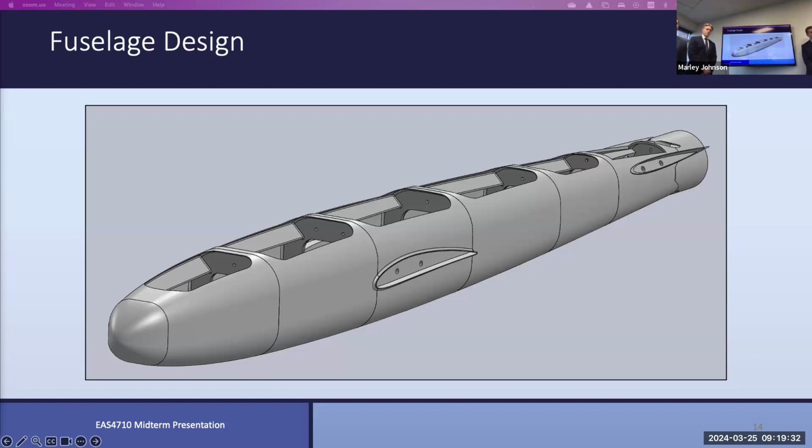So as long as you're able to show, back to structural analysis, assuming that all your load is going through the longerons, the stringers, whatever you call them, then I think it's okay. And nice generous corners, right? So you're not driving stress risers, although I'm not sure how big a problem that is in plastic. But nice generous corners, I'll let you look at that and see.